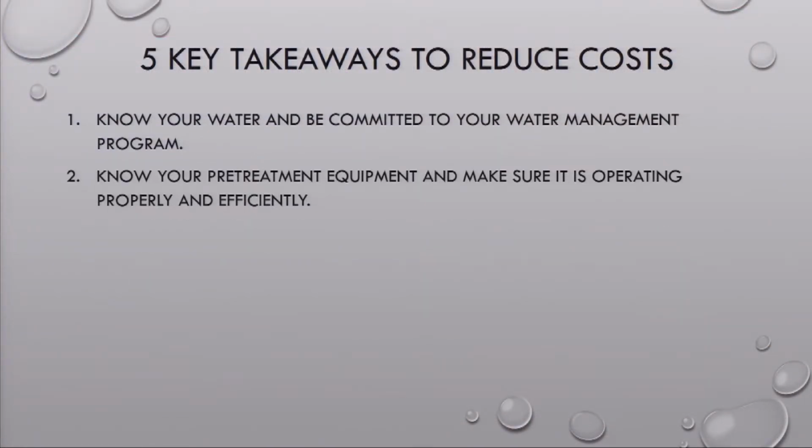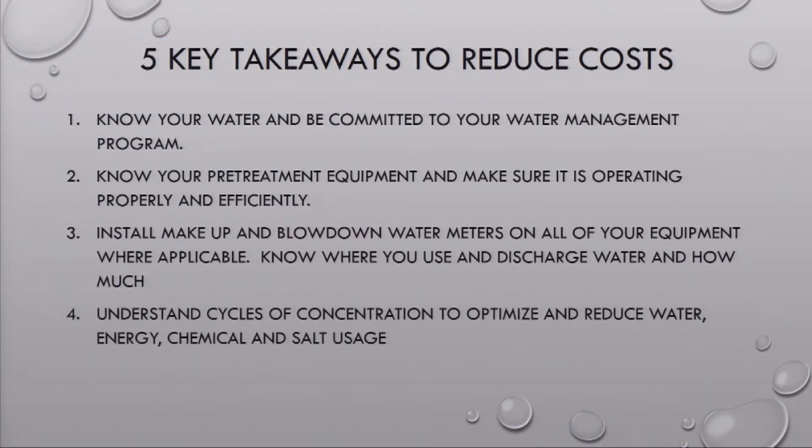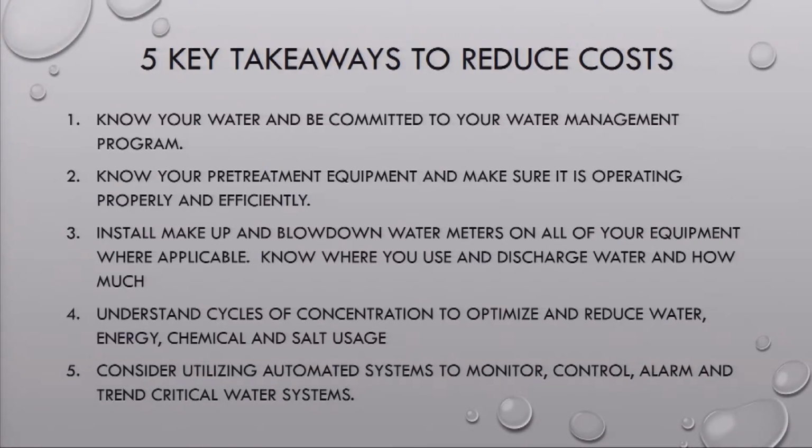So here are some takeaways specifically. Know your water program. You don't have to guess on what to do. We're going to push you in the right direction. Know your pre-treatment equipment and make sure it's working, especially for boilers.